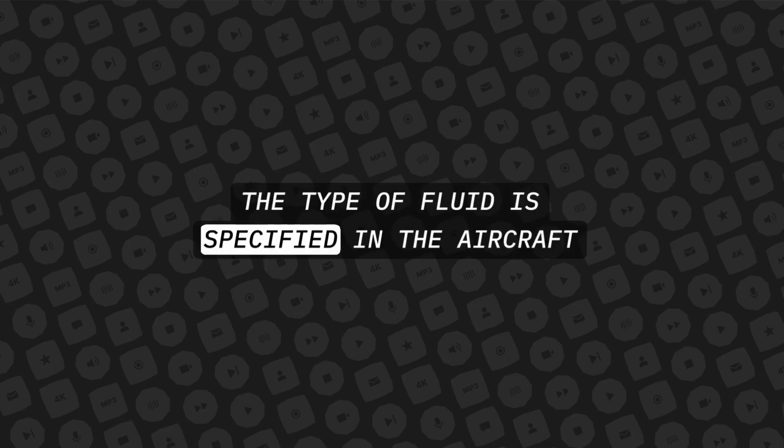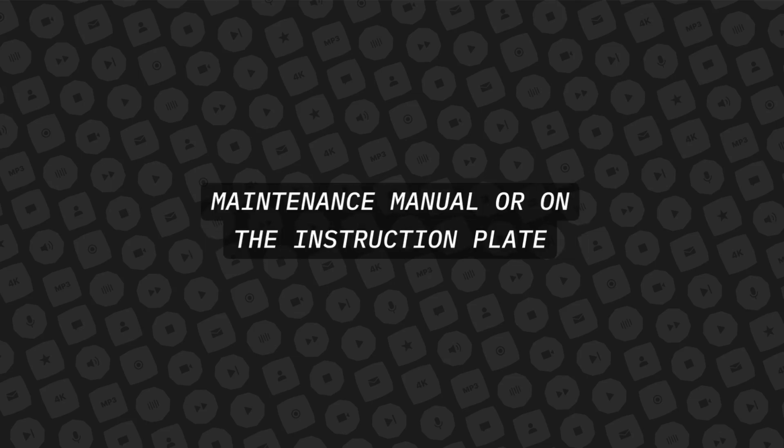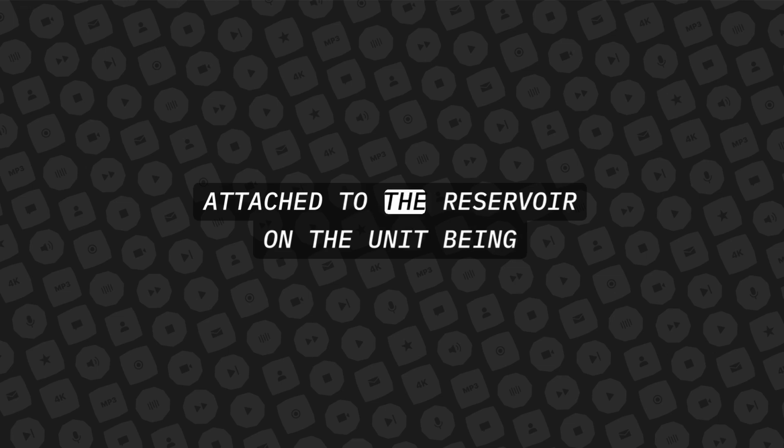How do you determine which type of hydraulic fluid to use in a specific system? The type of fluid is specified in the aircraft maintenance manual or on the instruction plate attached to the reservoir on the unit being serviced.